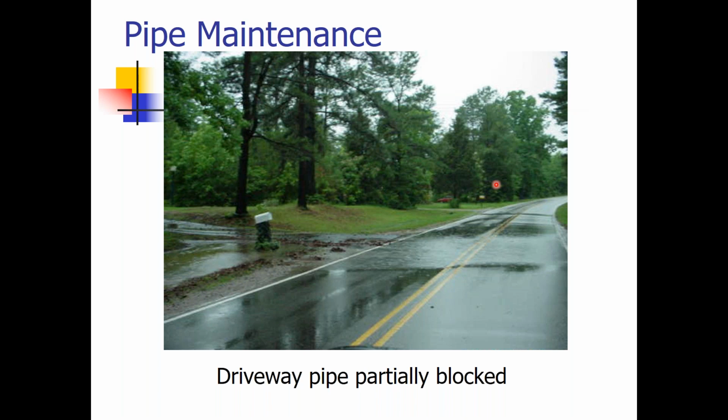I mean, it's at the point now, I don't know if everyone's familiar, you probably are, with what's called intelligent compaction. I can sit at my computer in my office and I can tell the rolling pattern, how well we're getting compaction in different areas of the road. It's gotten that far technologically. So you want to have compaction as much as possible using the best equipment that you can.